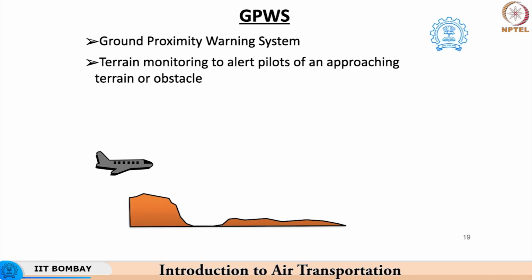Whenever such an altitude is reached, the GPWS system becomes active, and carries out regular monitoring of the associated hazardous flight conditions. Based on the presence of such a flight condition, the GPWS system will send a visual as well as oral warning signal to the pilots.